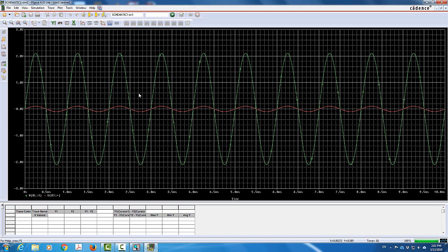So you can see, for example, when the input signal is positive, the output signal is positive. So the gain becomes a non-inverting gain, right? It's basically positive when the gain is positive. And you can see that Vout will be a little bit higher than 2 volts. In fact, it is going to be 2.1. Each of those divisions is 0.2, so it's halfway through the first minor division. So this is 2 volts, and then halfway through it's going to be 2.1. So clearly the gain is +21 volt per volt.